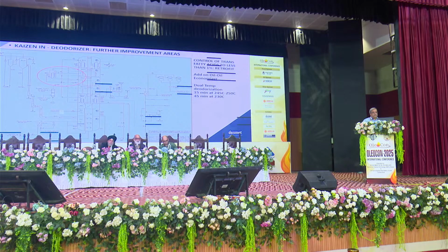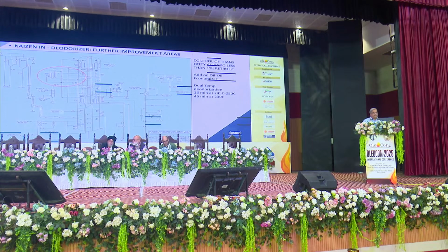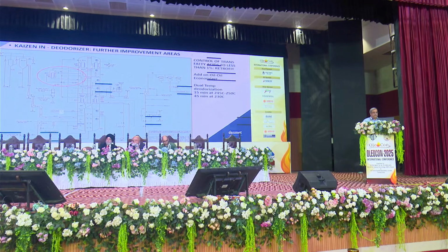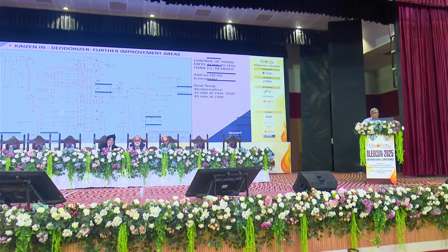Similarly, an external oil-to-oil heat exchanger, if it is added to a conventional deodorizer, we can run the deodorizer as a dual temperature deodorization. So typically 15 minutes we can run at 245 to 250 degrees. 45 minutes we can run at 230 degrees, and we can control our trans.